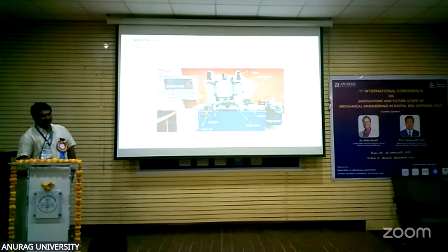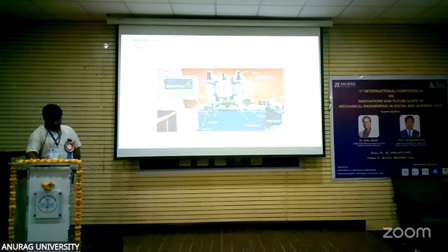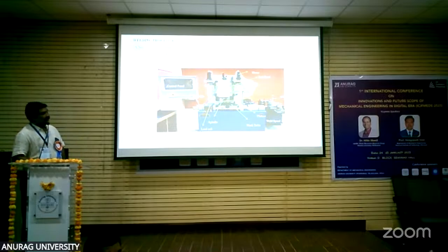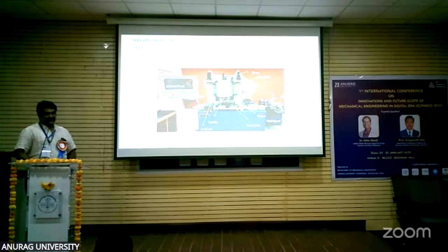On the basis of the profile, you can change the speed and feed. Now my basic question is: on what parameters or basis did you finalize the speeds, say 900, 1350 or 1800? Is there any basis for that? I can recommend from my experiments that we go for 1350 spindle speed. As per the experiments, 1350 and 26 gave the best. Yes, sir. But on what basis did you take 900, 1350 and 1800? Why 900 first? Why not 600 or 1000?